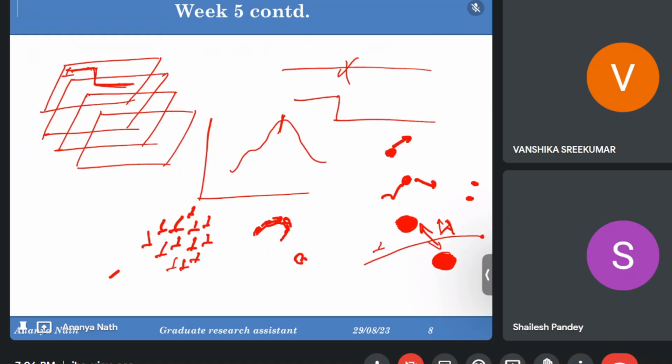But at the same time, because of this pile up, we need to move these dislocations. There our motive was something different, to lock the dislocation movement, but here we want the dislocation to move, and also at the same time we want the dislocation to move faster to get piled up. So cross slip is one phenomenon which is really needed for this type of cold working strain hardening.